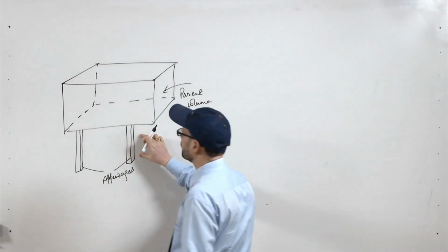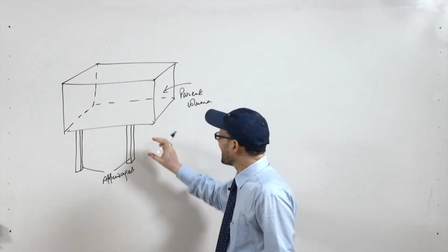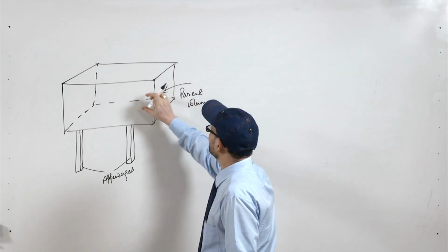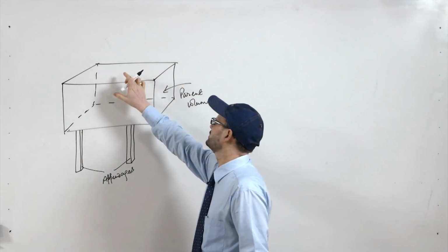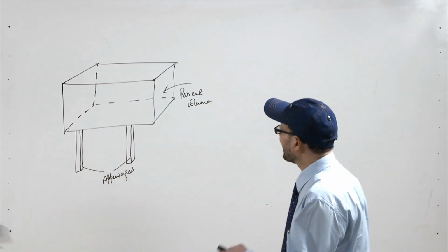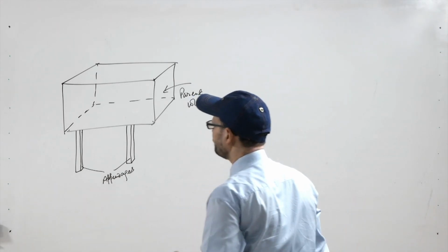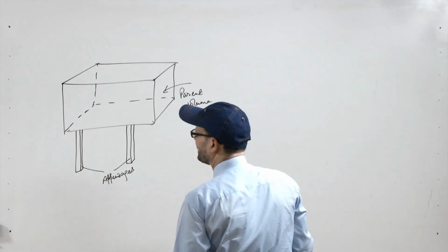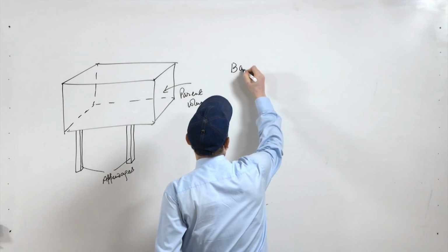However, if they are not thin, if their dimensions are considerable, then you need to supply certain extra material when you give the riser dimension for this particular casting. In fact, that has also been proposed in this particular method. Now these appendages are normally classified as bar or plate.